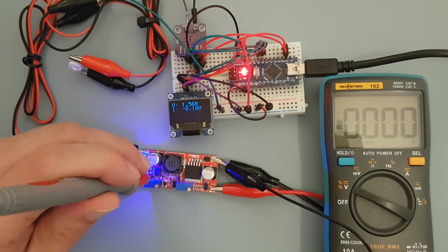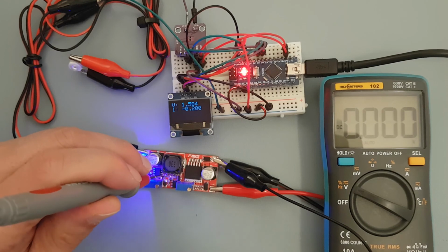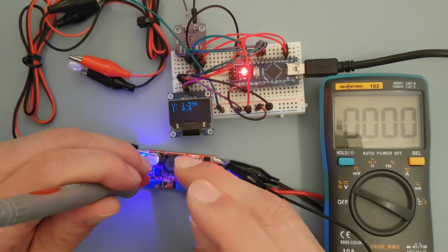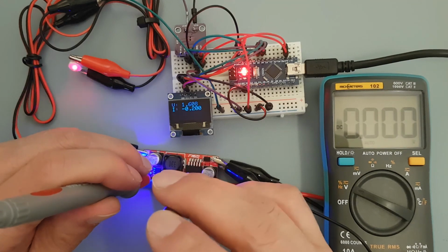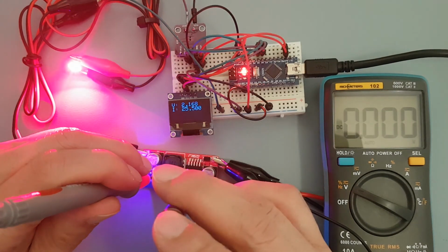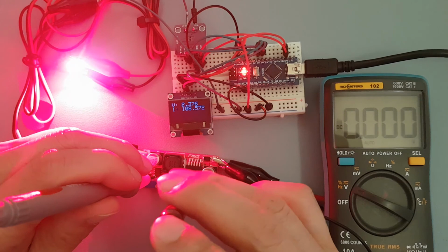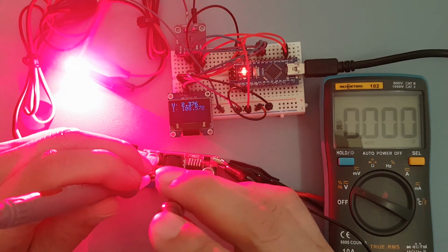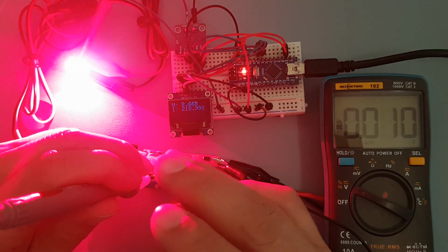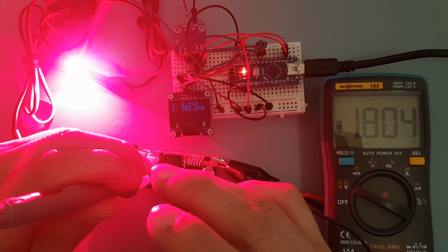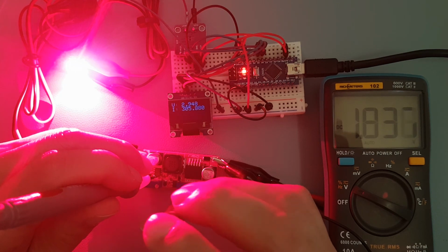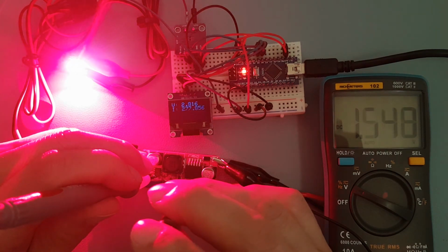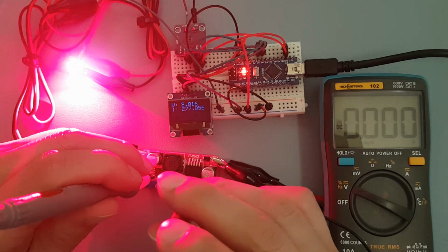Finally, let's look at the change in the output of the LM358 connected to the feedback. Before reaching the current limit, the voltage is 0 volts. In this state, the output voltage can be controlled only by the voltage control potentiometer. If you increase the amount of current flowing through the LED by increasing the output voltage, the LM358 output drives 1.8 volts at some point. It is this moment when the current limit is reached, and from this point, the feedback is controlled by the LM358.